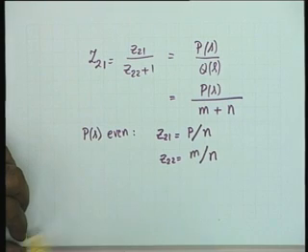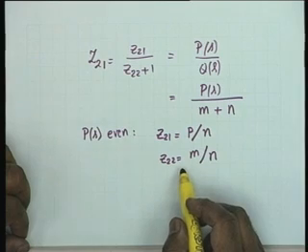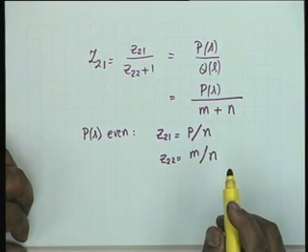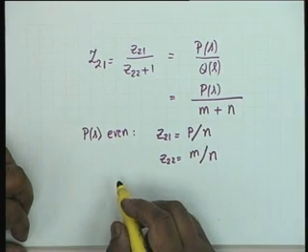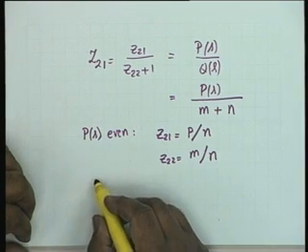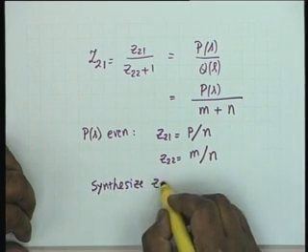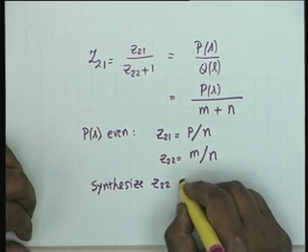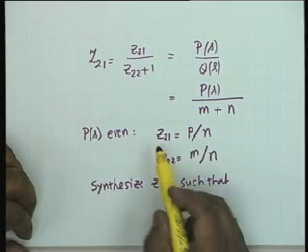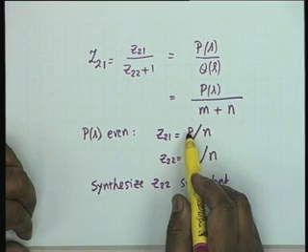We argued yesterday that Z22 is an LC driving point impedance because it is the ratio of the even to odd parts of a Hurwitz polynomial. The problem of synthesis then resolves to the following: synthesize the driving point impedance Z22 in such a manner that the zeros of Z21, which are the zeros of P, are realized.